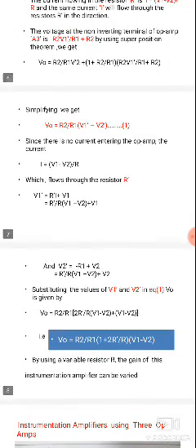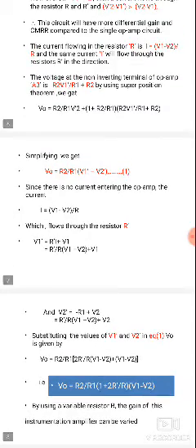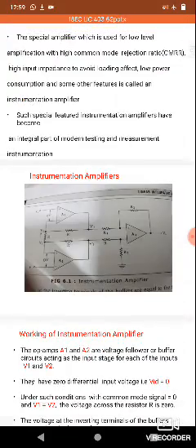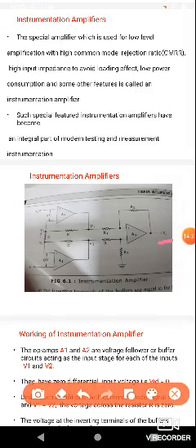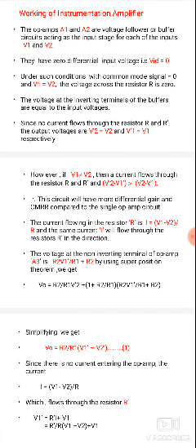By using the superposition theorem, we can get V0, the output voltage, which is related to the 3 op-amps. V0 will contain the values of R2, R1 and R dash resistors also. So V0 is equal to R2 by R1 V2 dash plus 1 plus R2 by R1 into R2 V1 dash by R1 plus R2.